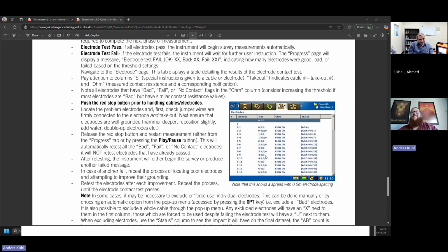So the ohm meters, that's the contact resistance, or the ohm. So that's this value here. And of course, in yours, you have no contact, so you have no contact resistance. But let's say you were in the field. You want this value to be consistent in the area. The absolute value will depend extremely on the ground conditions. But you want it to be consistent.